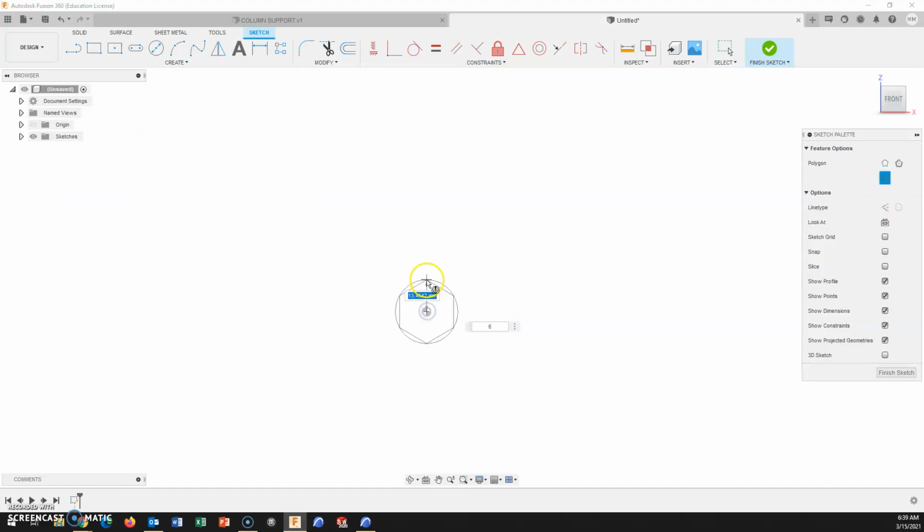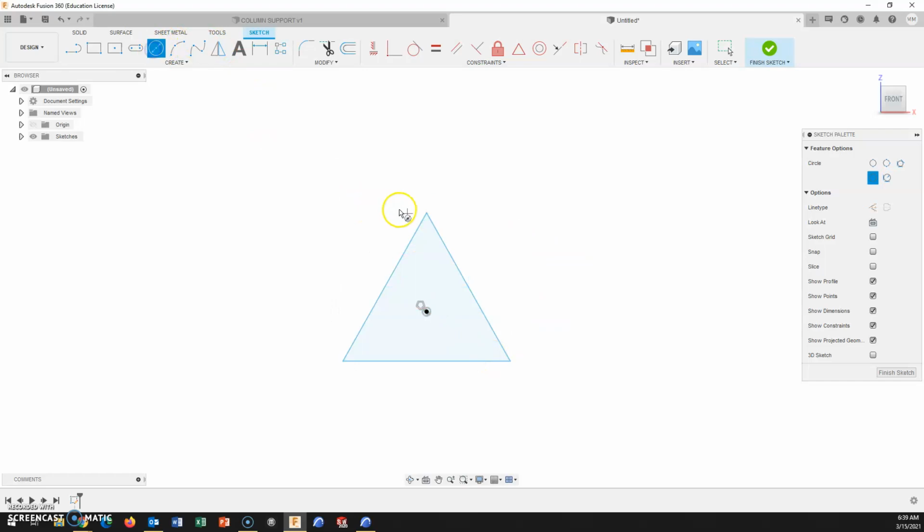So we construct like a circle. We radiate from the center out, and I'm just going to tab in to get the number of sides on the polygon. And I'm going to add the dimension as we start to create some features here. So we do have this outside radius. Now I happen to draw complete circles, but then we can offset these lines to then be tangent.